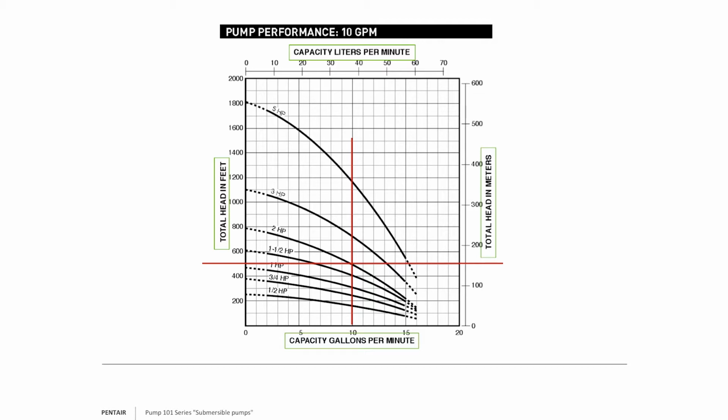But if I make the assumption that you need an additional 143 feet, now look at that. I'm looking at easily a 3 horsepower pump. I'm well over the 2 horsepower mark. I can't use my 2 horsepower, so I'm going to size you with 3 horsepower. And I'm going to oversize that pump if we misunderstood.